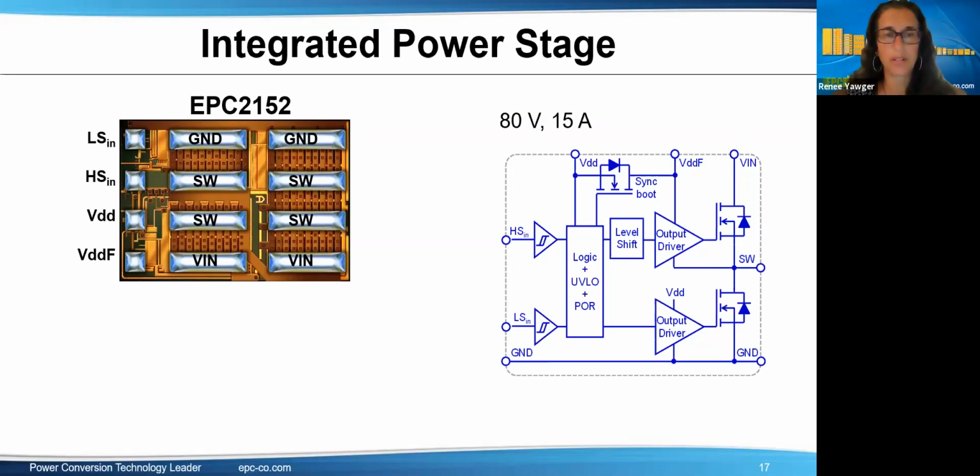Okay, so we have someone who's doing a design with the EPC2152. For simplicity and to limit size, it actively uses only the lower FET. The upper FET is always off and serves just as a clamp/snubber. When the upper FET is always commanded to be off by the control equals 0 volts, is it then needed to have a bootstrap capacitor at all? Yes, you really do.